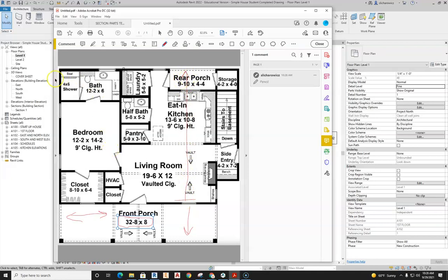So we need to look over here and say, well, here, let's look at some sizes. We got 4 by 6. Well, this is probably 6 feet in this direction. And then this room is probably 14 feet 2 inches in this direction. And then this is your 6'4" in this direction, okay? Plus, those are inside dimensions you got to think about, all right? So that's from the inside wall to the inside wall. Then we got space here for your stud. We got space here. And then we got thickness of this stud wall and this stud wall, okay? So when we add all this stuff up, we're going to have to give a little bit of an allowance, okay, for those additional walls.